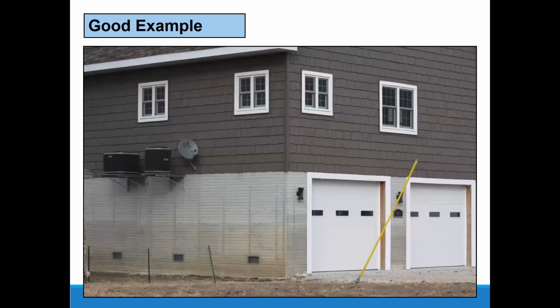So here's another enclosure. This is a full story enclosure. This is diagram 7. Basically you have a full story enclosure, usually functioning like a garage. It's used only for parking, storage, or building access. And then you have your living floor above that. You can see the utilities on the outside are elevated up to that first full floor, the living floor. And so they will qualify for the machinery and equipment discount. I have a slide on that, but basically they have elevated it so it's safe from flooding.